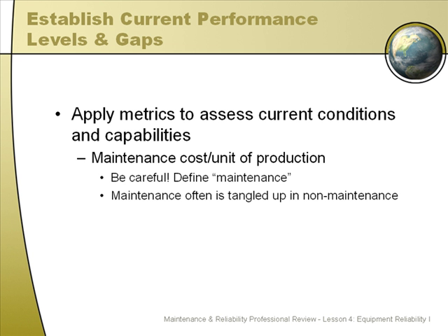Here's another important measure: maintenance cost per unit of production. Be careful here, because people are going to throw this number around and they're going to tell you that they have X cost per ton, and you're going to be trying to match up to that because you're in the same industry. Very tough. It's a dicey situation because many places measure their maintenance costs differently than others. You need to make sure that you take the time to be careful and define what maintenance means at your facility. We're going to talk about this in a couple slides here as we move along.